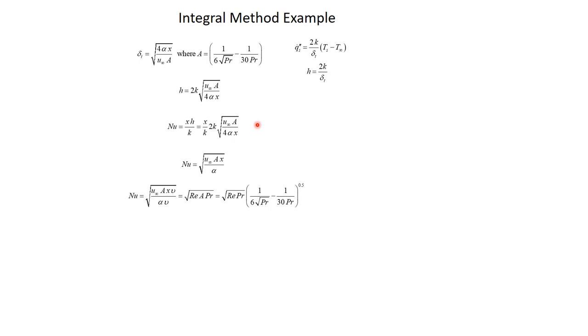The Nusselt number ought to be something that I can express in terms of Reynolds number and Prandtl number, right? That was the whole point of the dimensionless analysis that we did. We showed that Nusselt numbers are functions of Reynolds numbers and Prandtl numbers, provided you're not including viscous dissipation, which we're not here, and for a specific shape, which we have here, right?